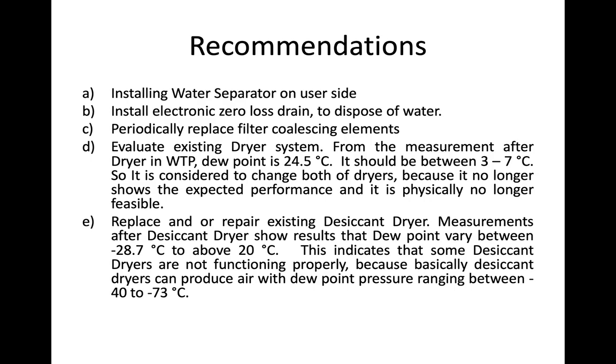This indicates that some desiccant dryers are not functioning properly, because basically desiccant dryers can produce air with dew point between minus 40 to minus 73 degrees Celsius.